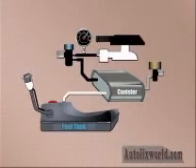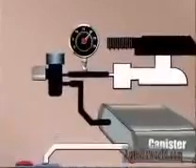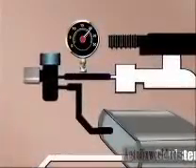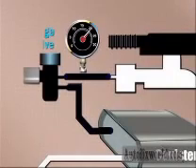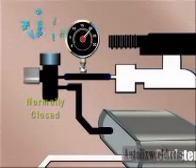Here's a brief generic strategy describing how engine vacuum is commonly used to test for leaks. Let's look at the main components of this system. A purge valve is placed in the line between the canister and the engine vacuum source. This valve is normally closed and is opened by a signal from the vehicle computer whenever it wants to purge fuel vapors from the canister to a running engine. This is no different from purge valve operation before OBD2.